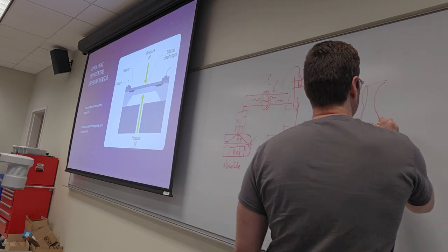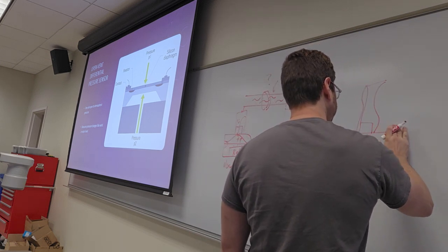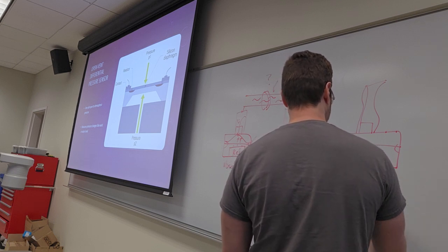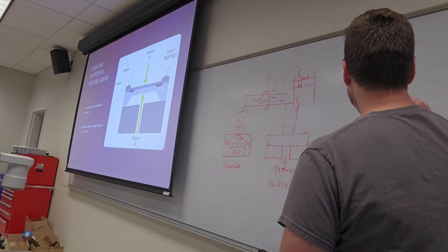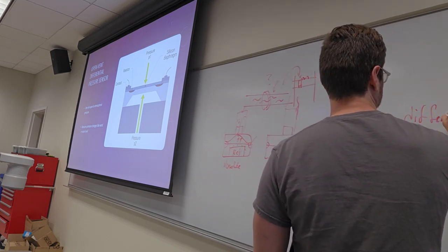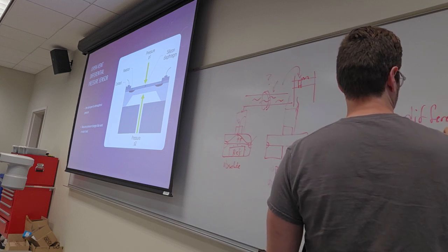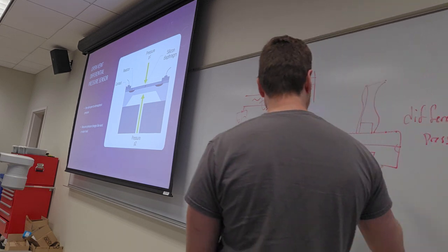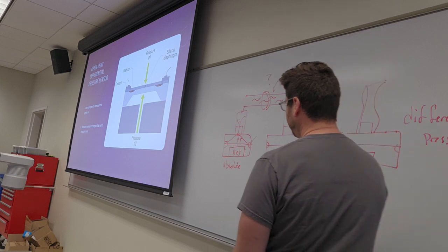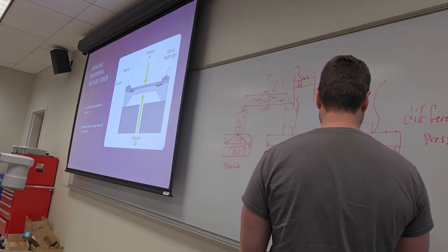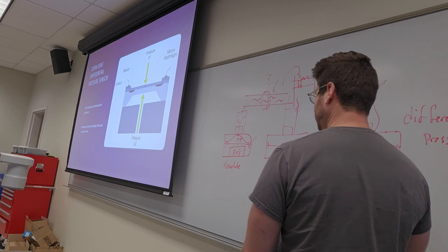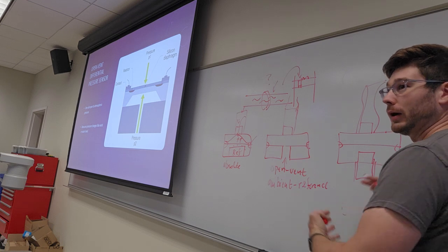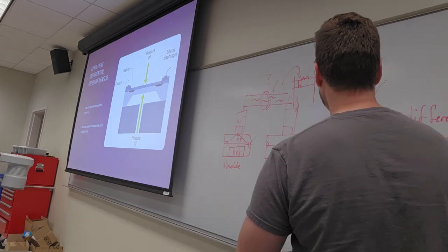Okay, this one is probably my favorite because it's the most flexible. You can use it in any of these conditions, depending on where you place this other port. But here we have the differential sensor. So you guys see here that I could make a differential pressure sensor into an absolute pressure sensor if I wanted to, by having a volume of no pressure here, right? Or I could make it an open vent by just exposing it to air, or I could make it a true differential by plugging this other hose into something.